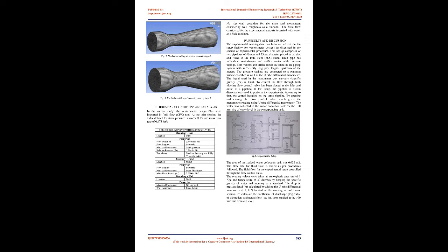8. In conclusion, they have found out the divergent section having an angle of 15 degrees has higher sensitivity in comparison with the other range of angles in the same. For the convergent section having an angle of 10.5 degrees with the divergent angle of 15 degrees is suitable for wet gas metering using Venturimeter in comparison with the Orifice meter.